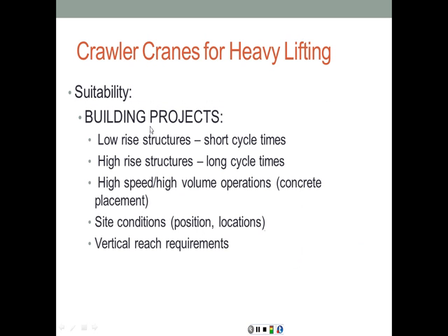It's suitable for building projects. Low-rise structures have short cycle times. High-rise structures are going to have longer cycle times. High-speed, high-volume operations like concrete placement. For site conditions, you have to select the position and location where you're going to locate that crane, and the vertical reach requirements to avoid contact with power lines and things like that.